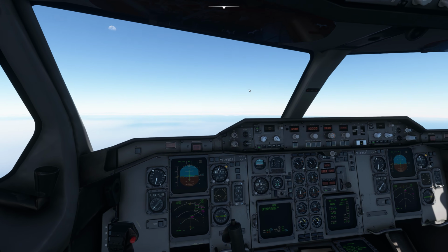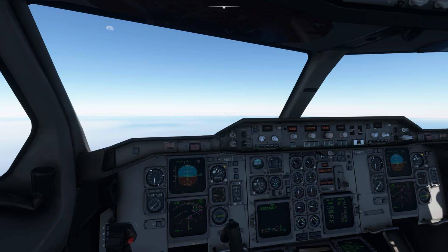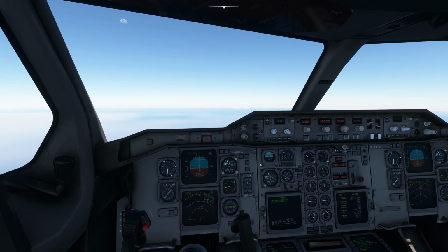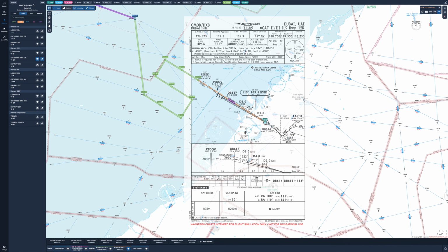As soon as you're within the given threshold, just activate the slats so that you're able to maintain the speed during the descent, because then afterwards I will be going to 210 knots and 185 knots at different points. So let's look at the approach plate again. This is the point DB657 over here. This is the final approach fix, and after this the plane will actually follow this glide slope.